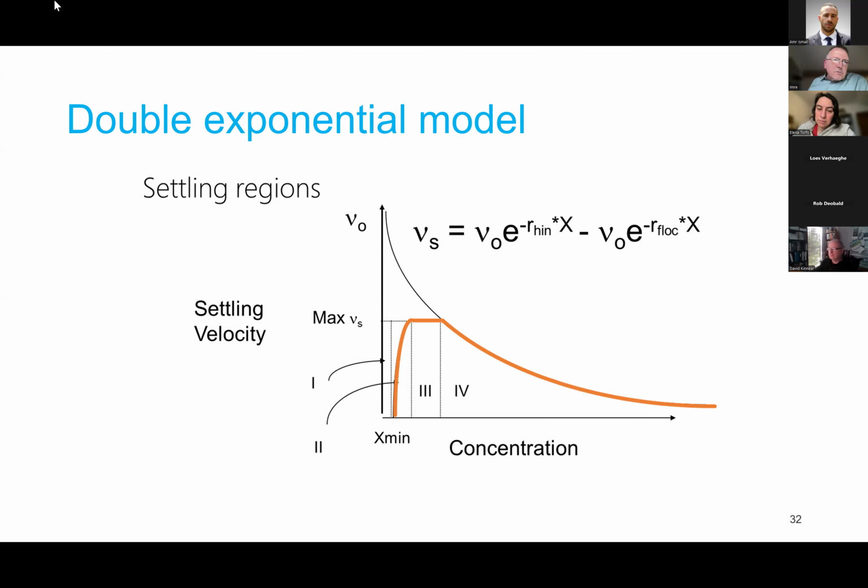But then we wrote another paper, which was a little bit beyond me, but Gilles helped with it, which describes that the bigger particles will settle a little bit faster, obviously. So what you essentially end up with at the top of the clarifier is a gradual size selection. Towards the very top are the smallest particles, with lower concentration, and a little bit deeper, but still above the blanket, you have the larger particles with somewhat larger concentration. So essentially, there is a link, and that's why this model does work.